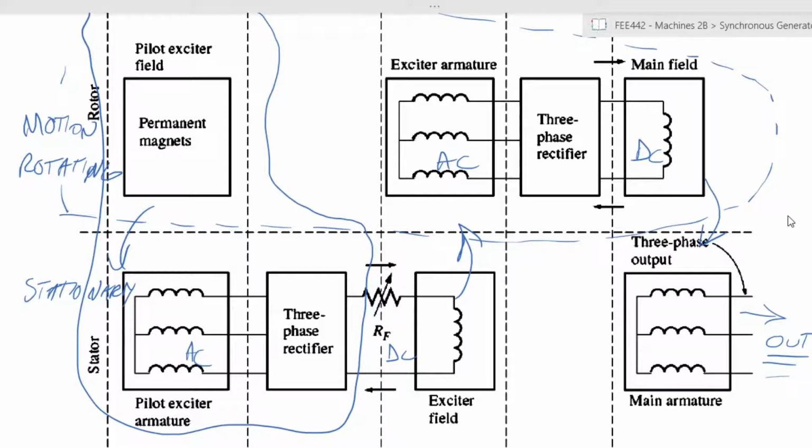It is kind of like amplifying. Generally, you would not have magnets that are powerful enough to provide a current that is needed. So it's almost as if it is like a two-stage generator, if I can call it that. Yeah. So each stage builds onto the next stage. Get it? So at the first stage, where you have your permanent magnets, the permanent magnets, by their interaction with the exciter armature, can generate a small current that is then pushed through. And at each stage, because you're inputting the rotating energy, at each interaction, every time you're crossing between stationary and rotational, you're almost adding the energy input of the rotation of the prime mover into that, and that becomes your amplifier. You're converting the rotational motion into electrical energy.